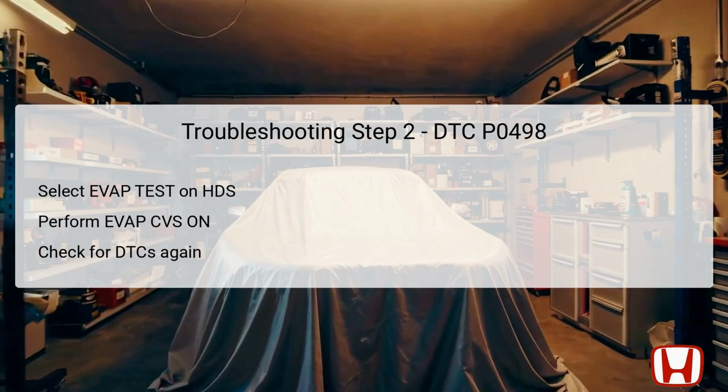After performing this test, it is crucial to recheck for any pending or confirmed DTCs utilizing the HDS. If DTC P0498 appears again, it confirms that the malfunction is a persistent issue requiring additional troubleshooting. However, if the DTC does not reappear, this may signify an intermittent fault condition, necessitating checks for poor connections or loose terminals at both the valve and the powertrain control module, PCM.